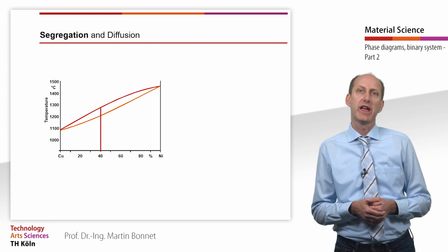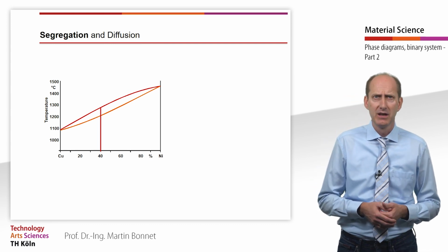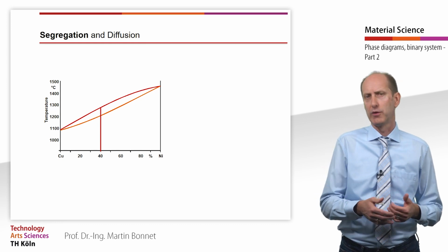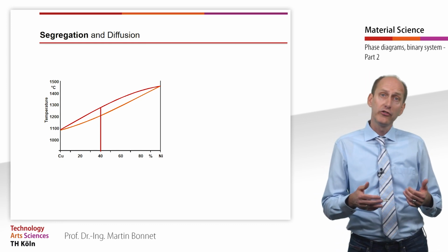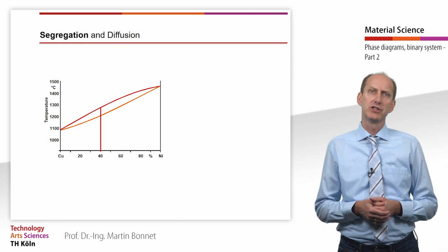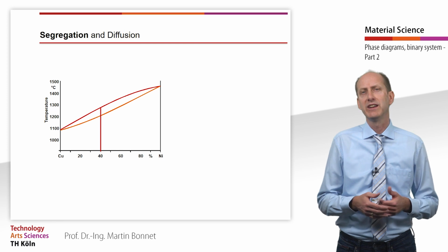As the composition of the melt and solid solution in the two-phase area changes constantly, unevenly structured inhomogeneous solid solutions are formed from the melt. This is also referred to as segregation. The internal composition of the solid solution is uneven.